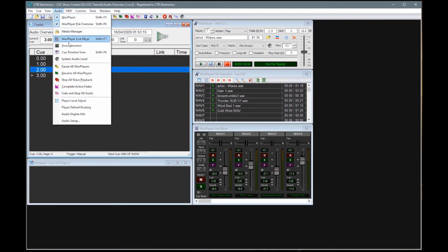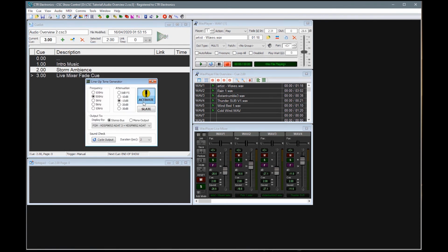When the time comes for gain matching with the rest of the sound system, a known reference level can be generated in the Tone Generator module. By automatically cycling through the available outputs, correct patching with the rest of the system can also be verified.